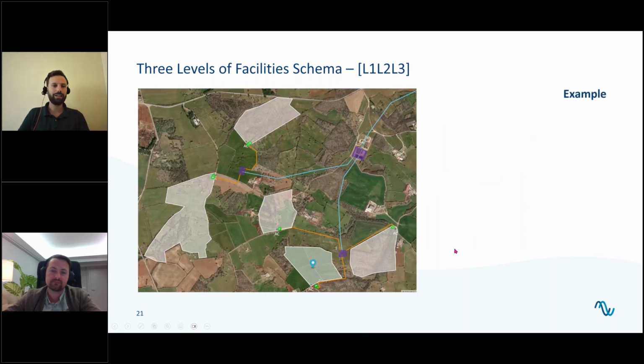Let's look at an example here. We have, in this case, 5 available areas. Each area has its own SBS in green. Those SBSs are collected, 2 of them in one substation over here, and 3 of them to another substation. The connection has been done using MV cables. And then from those 2 substations, we go to a pooling substation over here using overhead lines in light blue. And from our pooling substation, we go to the point of interconnection using that optional overhead line.